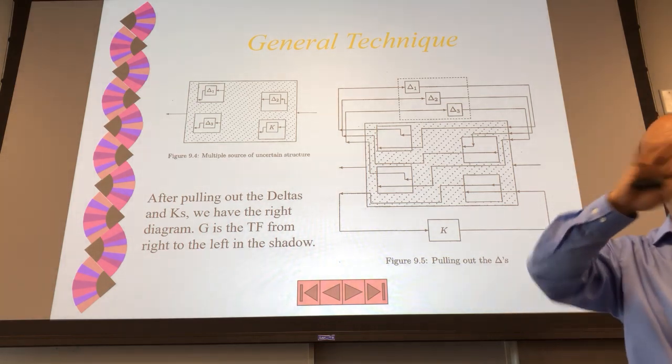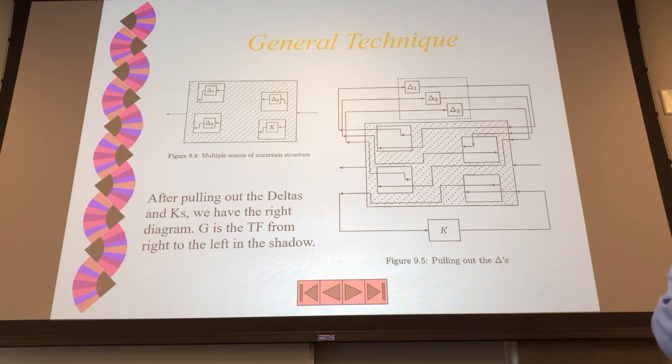Okay, you can pull out all of them, you just get block diagonal, like each block might be fully populated, okay? But I have different sub-blocks. So this could be a scalar or a matrix. And inside here, we assume this is unstructured anymore. Unstructured, not the structure I assumed, because you don't have a way to separate these. So while you pull out this one, you are already using what I call prior knowledge about the plant's physical parameters, and so on and so forth.